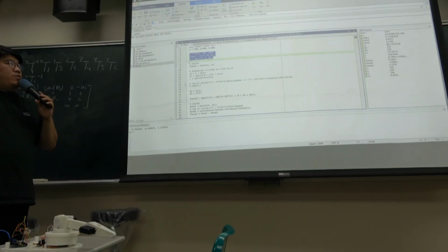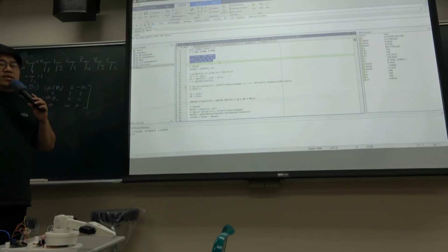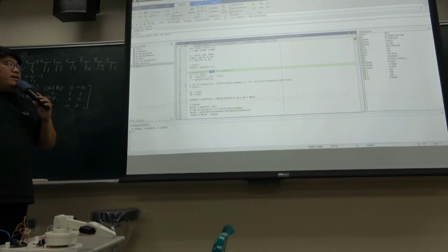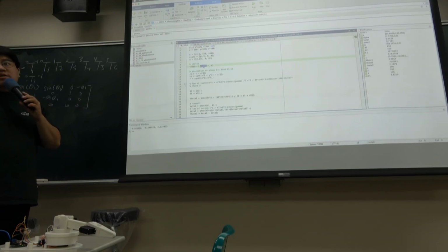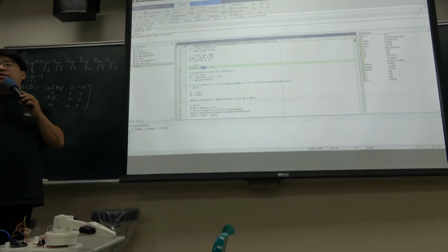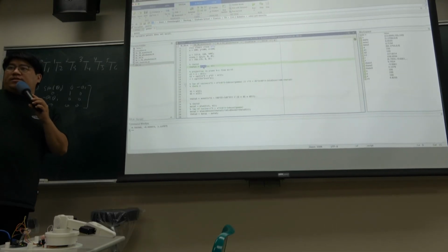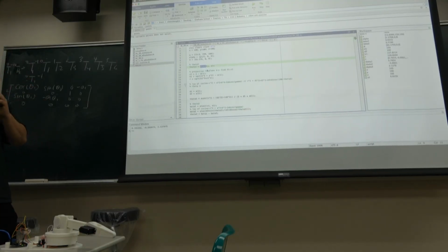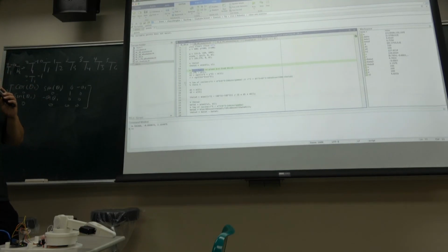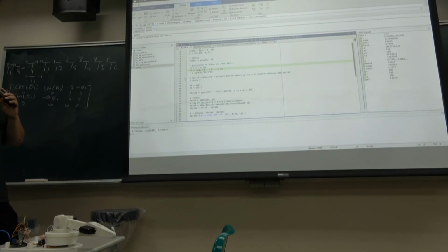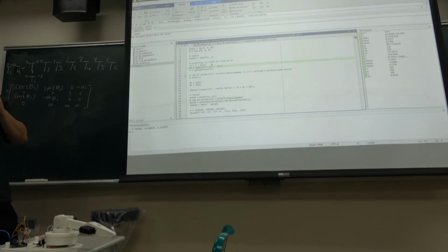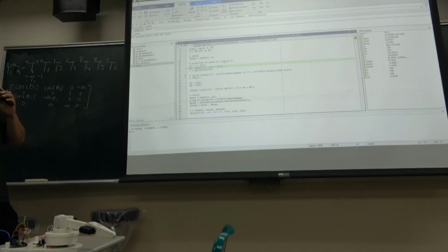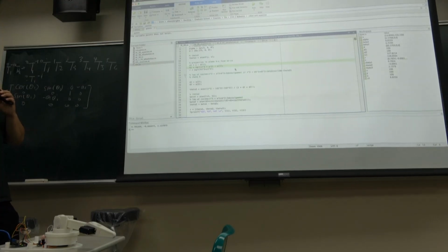And we already have the DH table of this robot. And then we solve theta 1 first, because just like I said, only theta 1 will impact the position on the XY plane. So it's an easy one. After solving theta 1, you can find the projection on YZ, XZ, and then find a new plane.